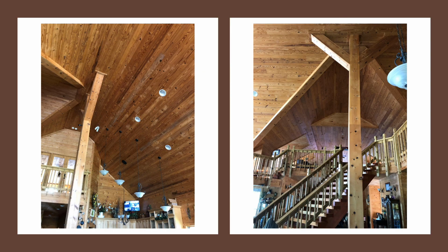The same lodge that you're seeing here has other unique challenges, like your ceiling height of about 30 feet. You've got hollow chase wall beams and support structures through here that create challenges when you're dealing with that. A challenge in itself is 3/4 inch planking that's wet. It's like drying a hardwood that's on a ceiling. Once again, take some of these light fixtures out, look in those holes, see what you're drying, and figure that out.